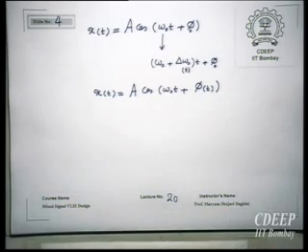Now, it is not limited to this. Suppose you have transistors, and all MOS transistors have flicker noise. And flicker noise is a low frequency noise. Flicker noise can change the bias point of a transistor, simply, right? Therefore, the effective current you get from a transistor, a DC current, is not constant.